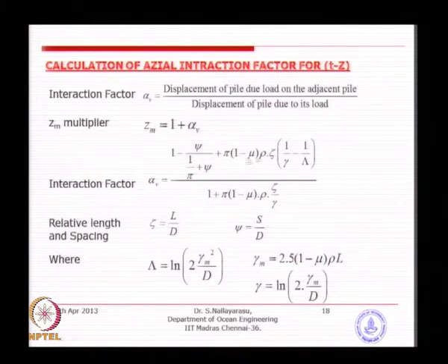If you substitute here, it will become too big, so that is why I have taken a few subdivisional parameters. What is involved are the spacing, diameter, length, then the variation of modulus and Poisson's ratio. These are the parameters involved in computing this alpha factor, which will be added in 1 plus alpha v. As long as you have a higher number, you will get the effect.